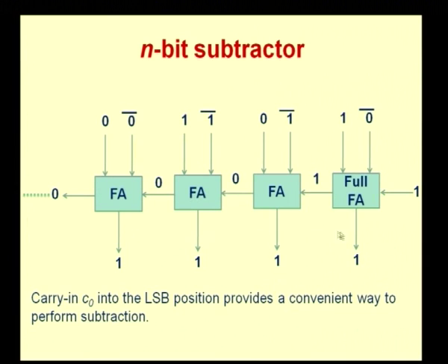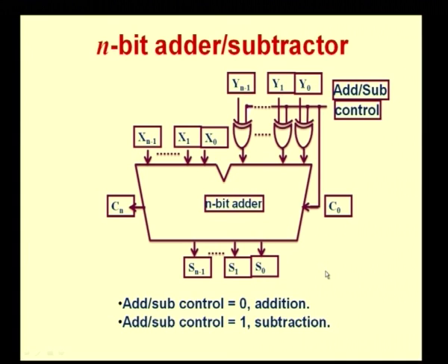You can look at it as a signed number that is being added. So, because when I did the subtraction, I have converted this number into its 2's complement. So, since we subtracted 0 1 1 0 from 0 1 0 1, the answer will be a negative number, which is what you will see over here. Now, the adder and subtractor can therefore be combined together into a single circuit.